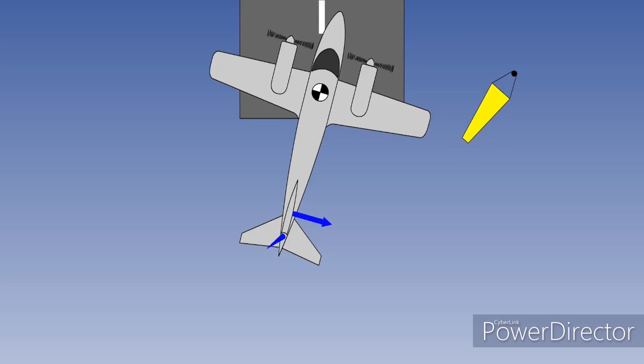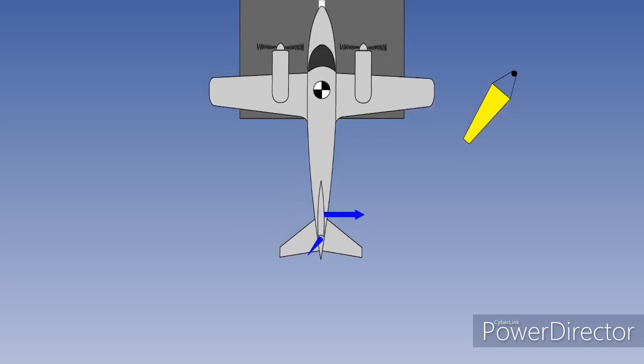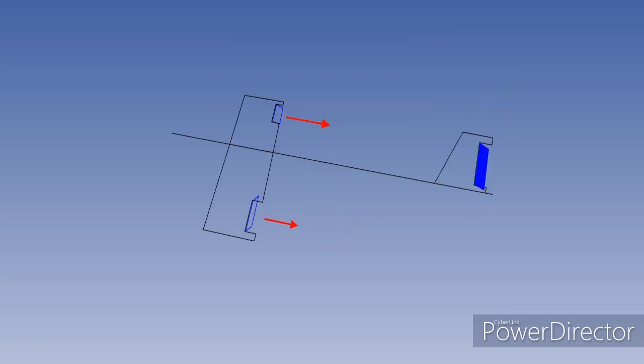You use the rudder to align the aircraft with its direction of travel. Not too early, or the aircraft will start to drift sideways. Not too late, otherwise you will damage the undercarriage. The third use of the rudder we will look at is something we have already considered: balancing adverse aileron yaw.